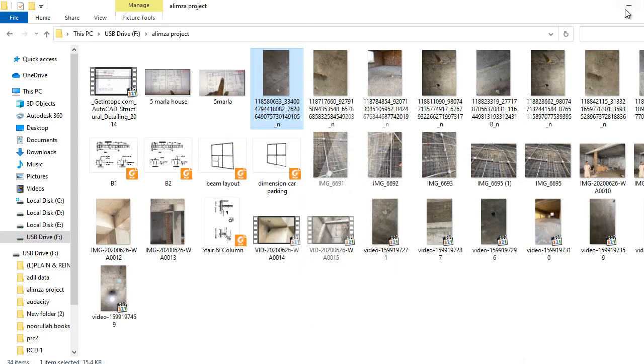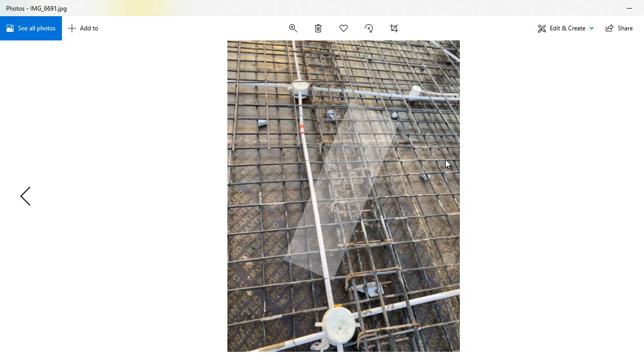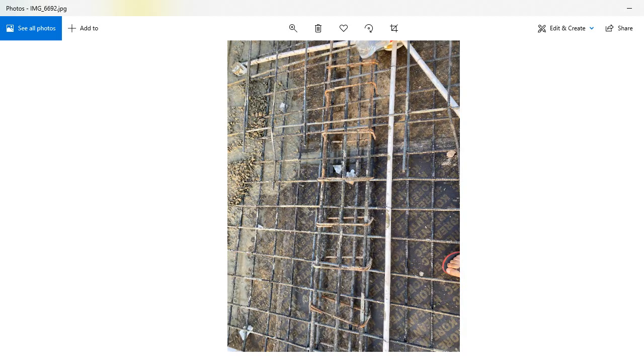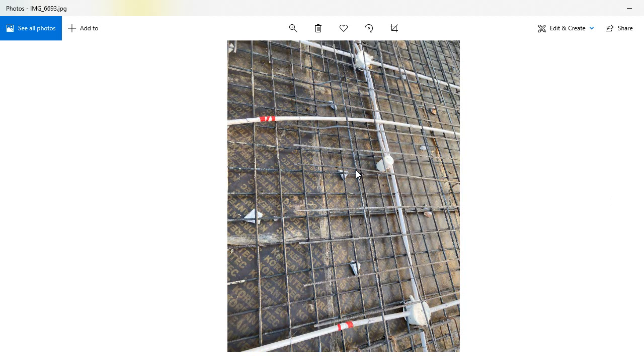Although the steel amount is perfect, and all other provisions are provided, the steel is fully according to the requirements of the ACI code, they did not maintain the thickness. So the deflection criteria is not satisfied and the slab system is cracked. So it is very important that you provide the ACI code criteria.